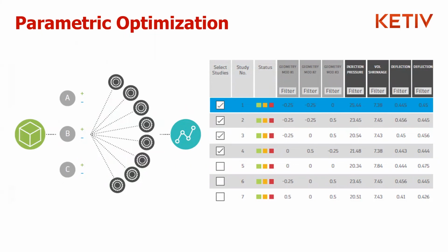And for each parameter, you can specify that range, whether it is wall thickness, cooling channel, the location of the cooling channels, gate sizes, etc. You will see those individual results. In this case, we're looking at shrinkage percent, for example, and the deflection with each single design iteration. So you keep going that way to identify what your best geometry is going to be, and then maybe combine that with the design of experiments to understand what your best process settings are going to be.